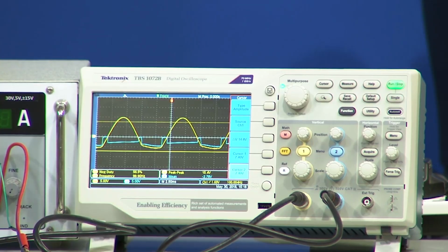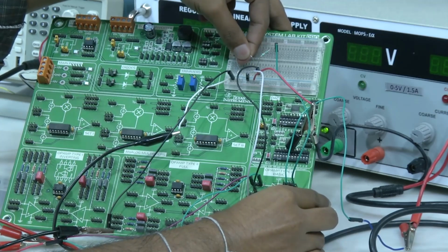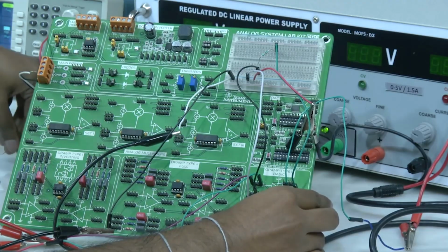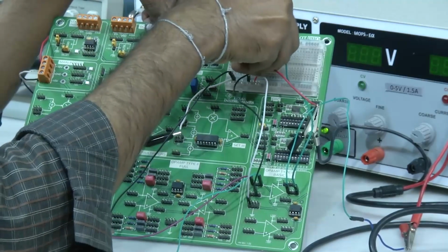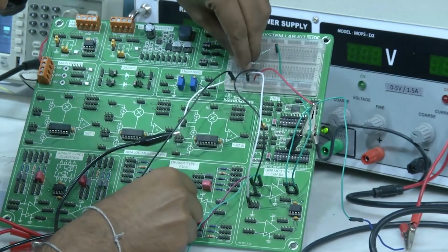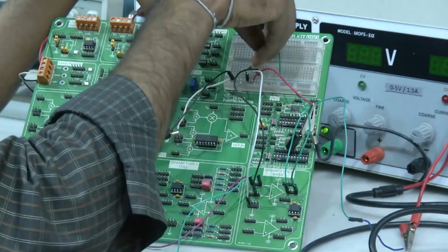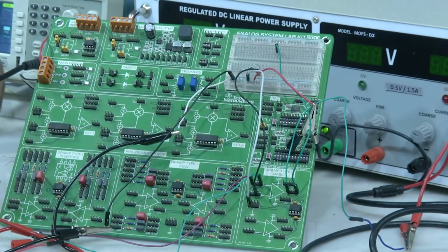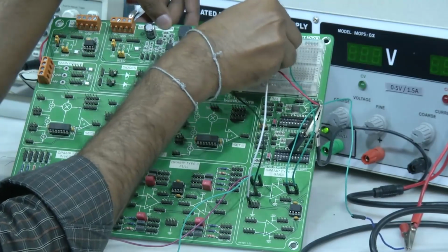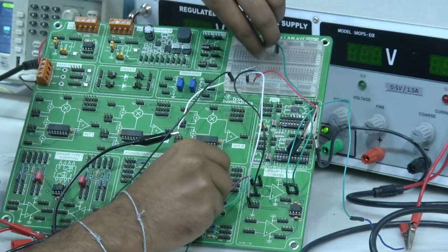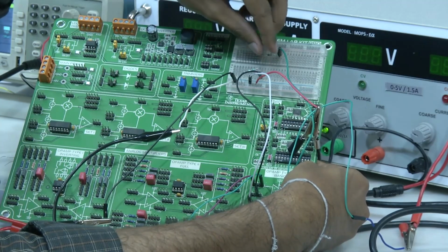When we focus on the board, we can see the 10K resistor is the feedback resistor. So, R1 is 1K resistor and R2 is 2.2K, so both the resistors have to be changed. Now we are connecting R1, sorry, R1 is 1 kilo, across ground and positive input terminal, and the feedback resistor is replaced with 2.2K. So, the beta value will become 1 kilo divided by 3.2K, which is 0.3125, and higher and lower thresholds are 4.687 and minus 4.687.